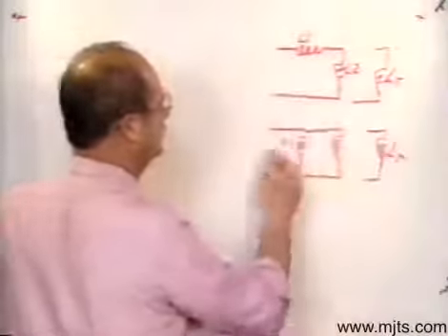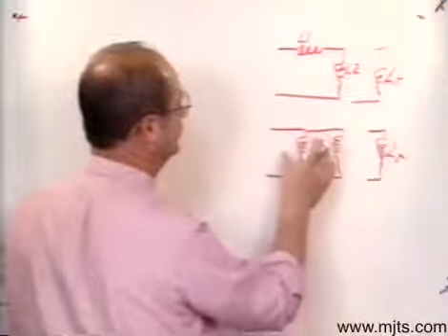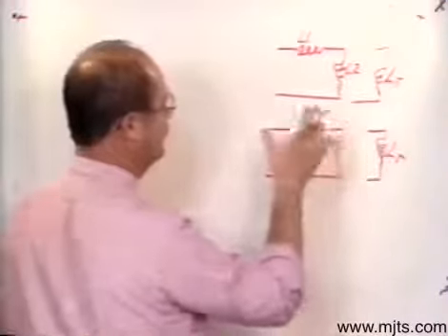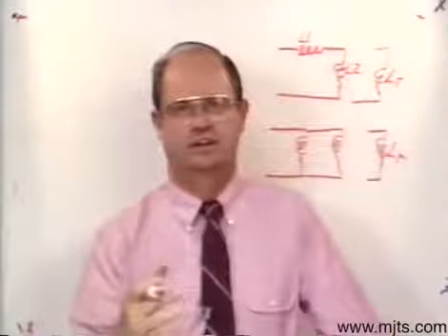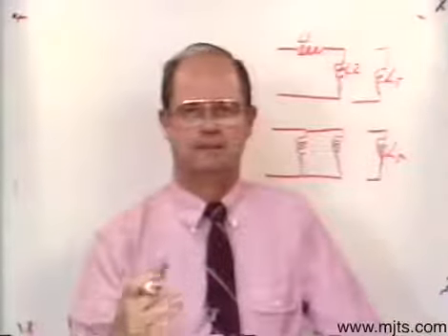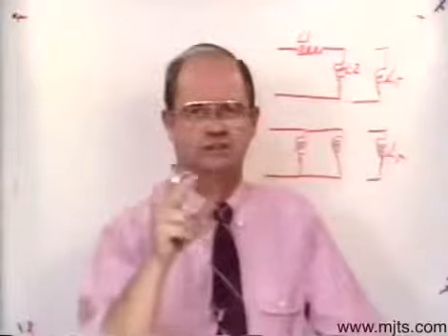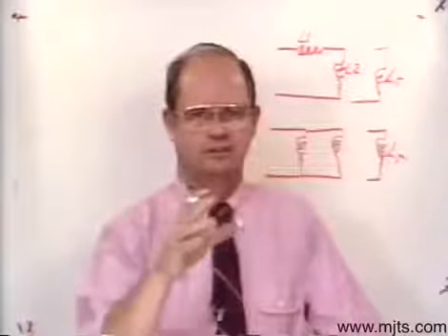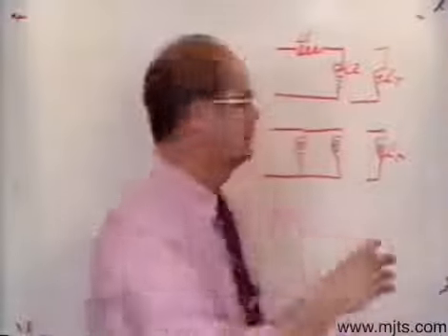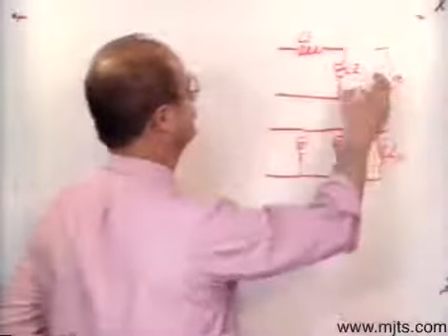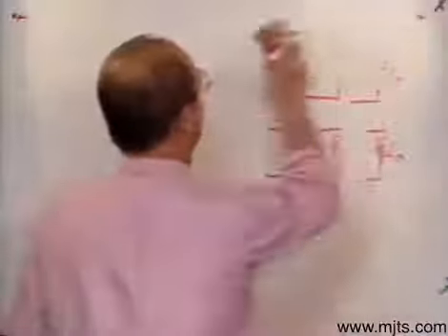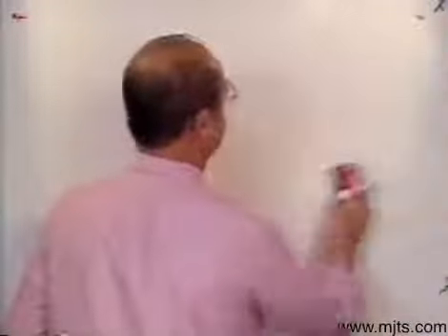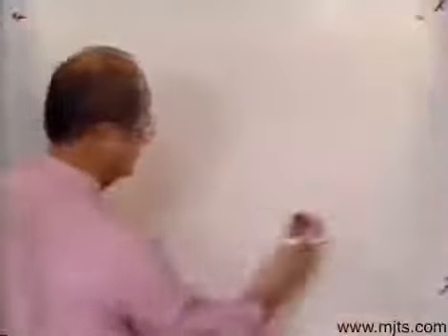And then when I have them in parallel, I would have my L1 and my L2, and I would use the unequal branch or reciprocal method, whatever the case might be. So you'll treat the inductors just exactly like you did the resistors to find your inductance total in either case. Okay? Now let's take a capacitor. Now you'll treat those just the opposite.